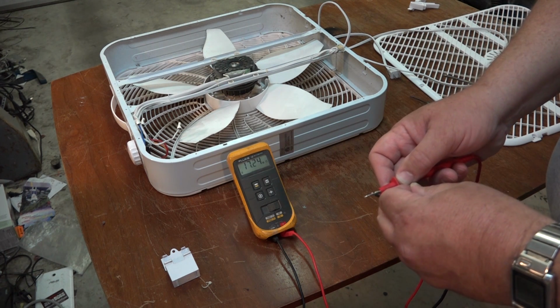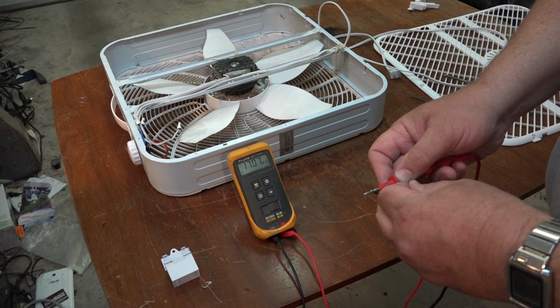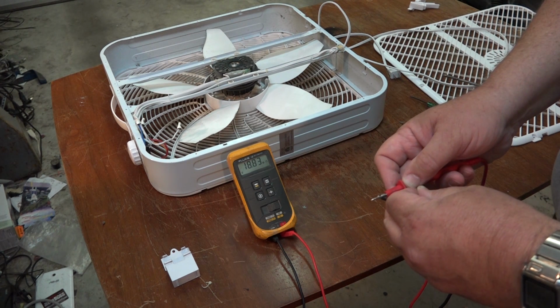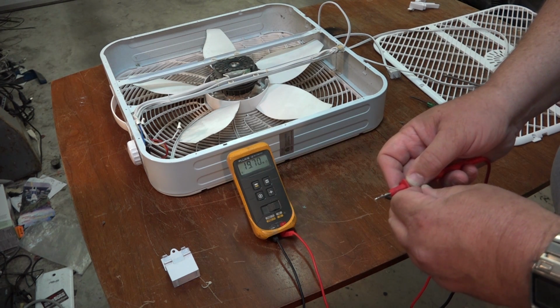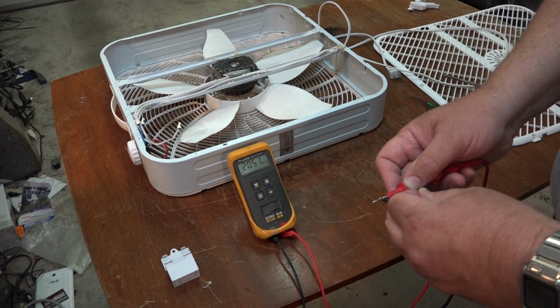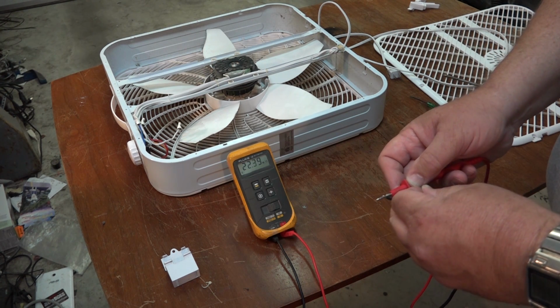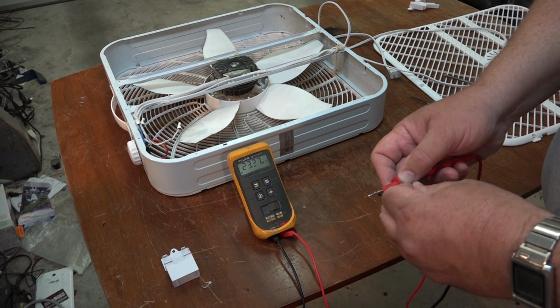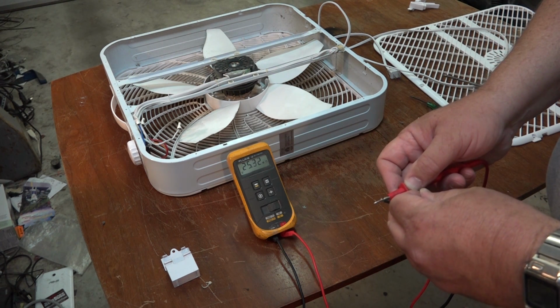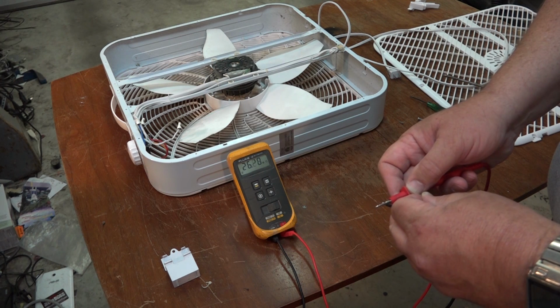And as you can see, as the capacitor charges, it resists more DC current flowing through it. And then my meter will go to its maximum range of 30 megohms here momentarily, and then it'll say overload.